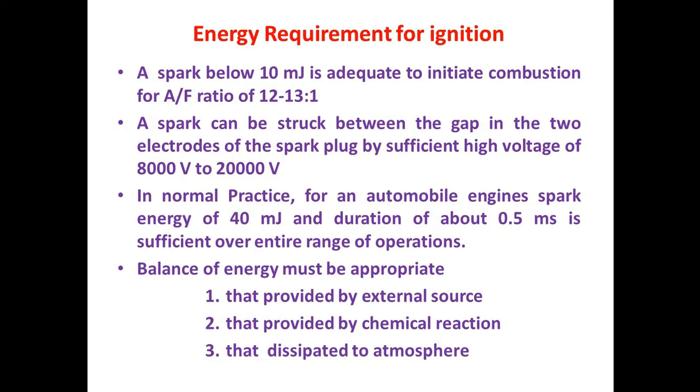Now, we will see what the energy requirements for an ignition system are. Here, for a homogeneous mixture, in order to initiate the combustion process, a spark energy of 10 millijoule for a few microseconds is required. Usually, when the spark energy is 40 millijoule for 0.5 microseconds, then very reliable ignition can be obtained.